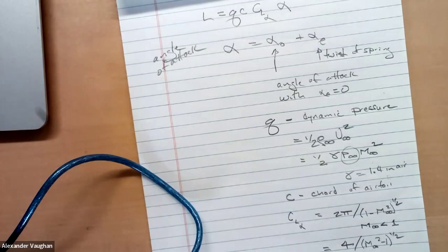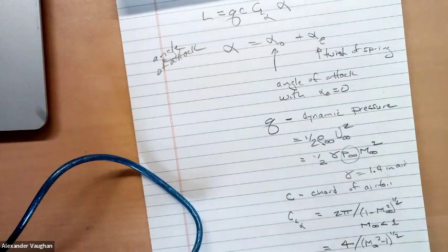What happens when the Mach number is equal to 1? Well, CL alpha seems to be fairly large. What that's really telling us is that these results, which come out of a linear model for the aerodynamics, basically solving the wave equation for the pressure on the airfoil, break down at Mach 1 in 2D flow. It doesn't break down in 3D flow. So I'm thinking of my model as spanning my wind tunnel from wall to wall, so the flow is uniform in the span-wise direction, and these are the results of that case.